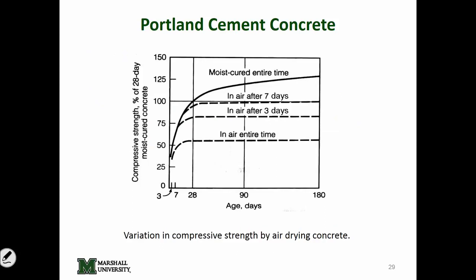The importance of properly curing your concrete. Do all the mix design in the world and get it perfect, but if we don't cure the concrete correctly, this is an indication of what kind of compressive strength you're going to get. Cast the concrete and don't do anything for it, dry it in the air the entire time, and when you thought you were going to maybe get 3,000 PSI concrete, you're going to get 50% of that. Your y-axis here is the percent of compressive strength at 28 days. So if you want to get the maximum value out of your concrete, you moist cure it, keep it cured while it's going through its hardening process, and you will get more than 100% of your design strength. The longer you leave it out, the lower your compressive strengths are going to be.